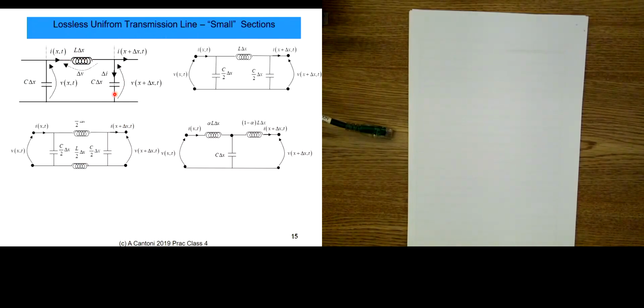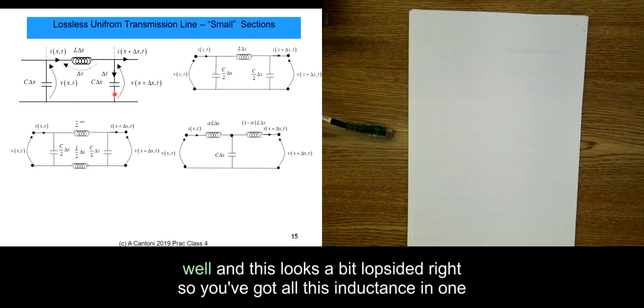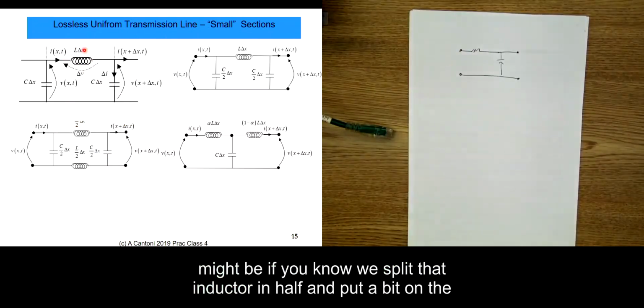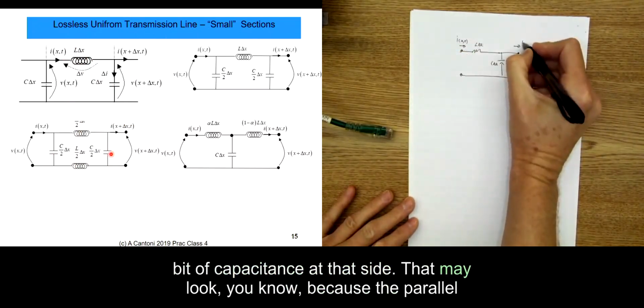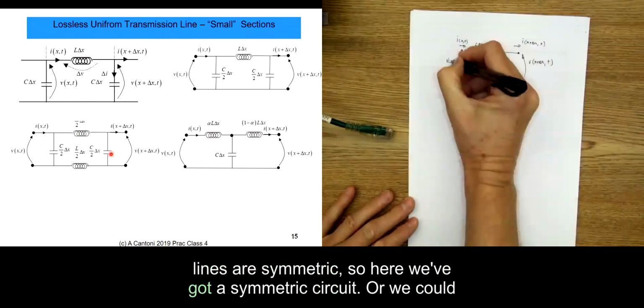But since we have these parallel lines and it's pretty symmetric, you might wonder, well, this looks a bit lopsided, right? You've got all this inductance in one place and all the capacitance here. Perhaps a better model might be if we split that inductor in half and put a bit on the top line, a bit on the bottom line, and put a bit of capacitance at this side and a bit of capacitance at that side. Because the parallel lines are symmetric, here we've got a symmetric circuit.